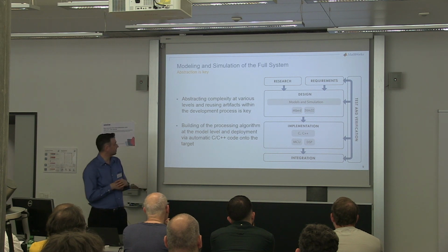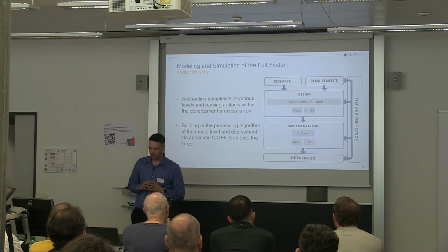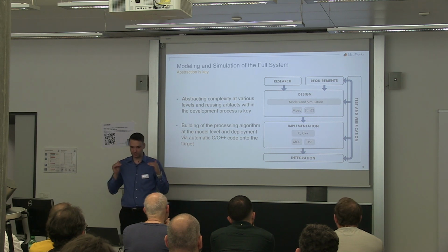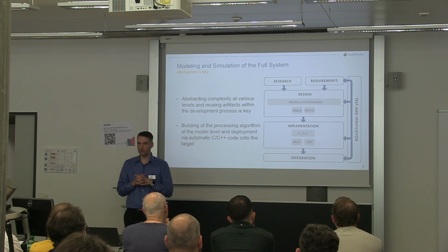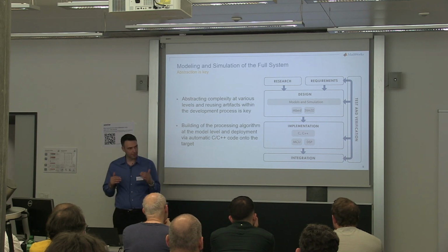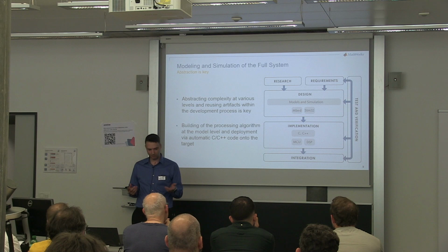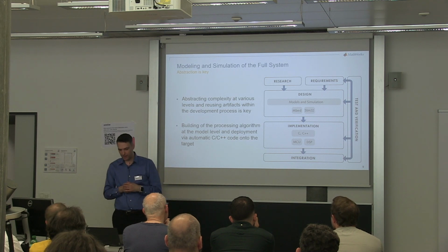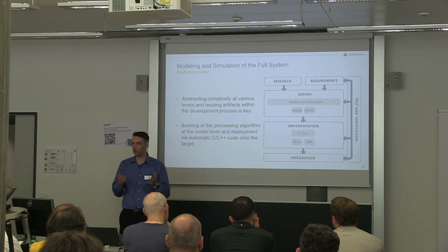Then here it's the modeling and simulation approach where abstraction is key. So you see, with the standard model-based design workflow, we start with the requirements at the very beginning, where you will collect your high-level system requirements. And then you will enter the design phase. In my case, in the design phase, I'm using Simulink with the type of data set that I have collected, either from the smartwatch or from the board directly. And here you can already prepare your model to go onto a specific platform.